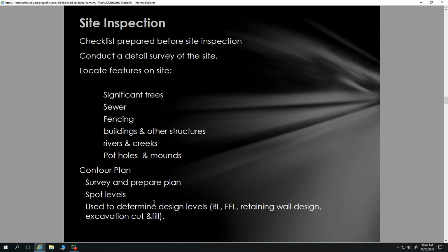Although I've also been to a site where we had to take soil samples within the hallway of an existing building. So take up the floorboards and do soil samples within the building. That was done by a two-stroke motor-driven ram with a push rod.